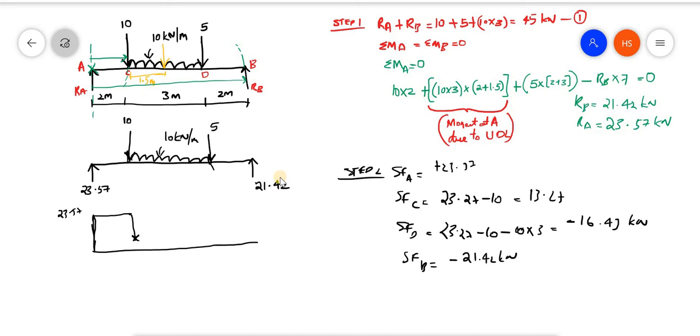So here a small thing is also there. Here I have taken 23.23 minus, this is considering the left side. So the shear force to the left here is minus 16. So here I am just marking to the left. Again, shear force at D to the right, if I am considering, what will be the value?